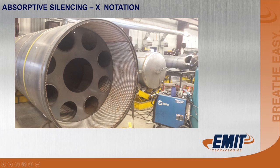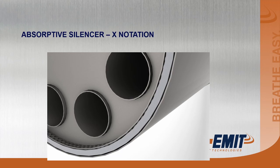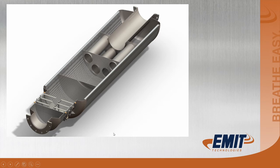Okay. Absorptive silencing, we usually put an X in the notation on the catalyst housing. So if you had an EBX, that would be an EMIT base mount with an X, and that has ceramic wool wrapped on the inside of the housing. Very, very quiet. Very great performance and sound attenuation reduction. Okay, so here's a model of it. So you've got your outer shell, you've got the ceramic wool, and then you've got perf plate lining that to hold the ceramic wool in place. Okay, there's what a cutaway view would look like.